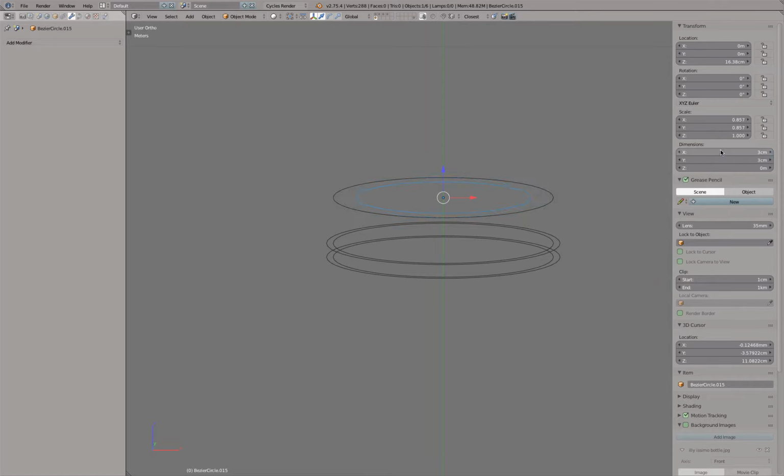Okay, and then everything sinks down just properly a millimeter. Yeah, roughly a millimeter. Okay, so Shift D, Z, minus 0.001. You see with the minus key, I actually flip the direction. So instead of moving it up 1 millimeter, we just move it down 1 millimeter. And then we can press enter. Perfect.